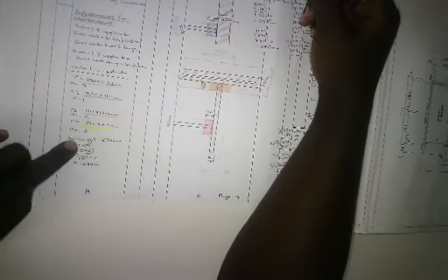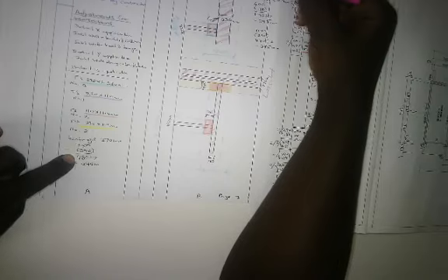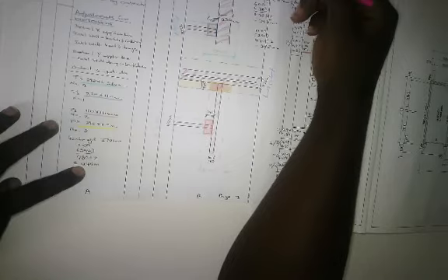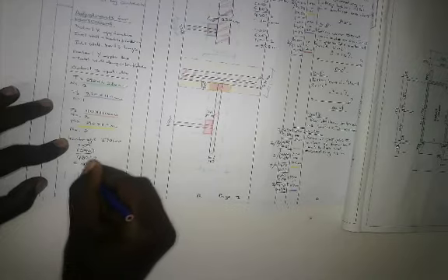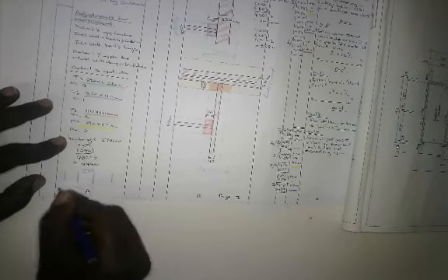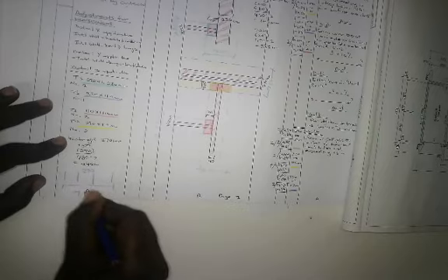So what we're gonna say is 750, which is the width of our 270 wall trench. We're gonna say 750 minus 270, okay. That's gonna give us 480, and then 480 divided by 2 is gonna give us 240.